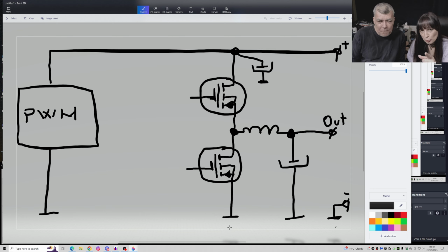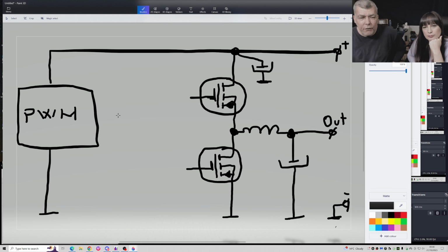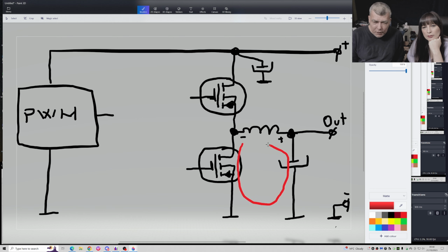So you have that capacitor connected to the ground. Exactly. That means it's connected to the ground. You will see the sign like that, or you'll see it like that, which is symbolized like the ground. So we have two MOSFETs, and we have the output of the PWM generator. You see, in this way, when the coil is bouncing back with the minus here and plus here, we can discharge the coil through the MOSFET.